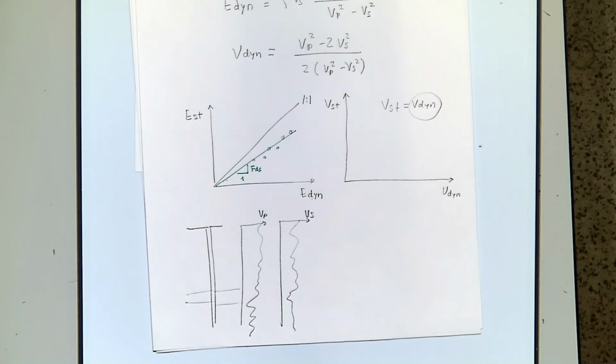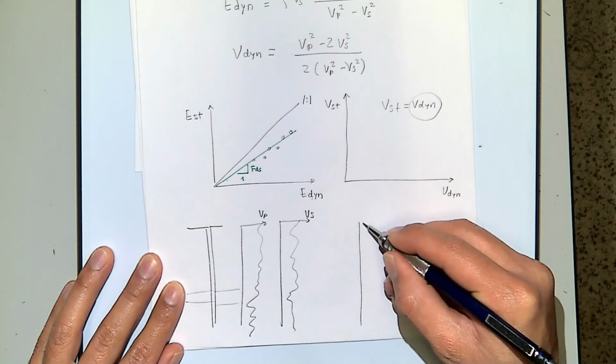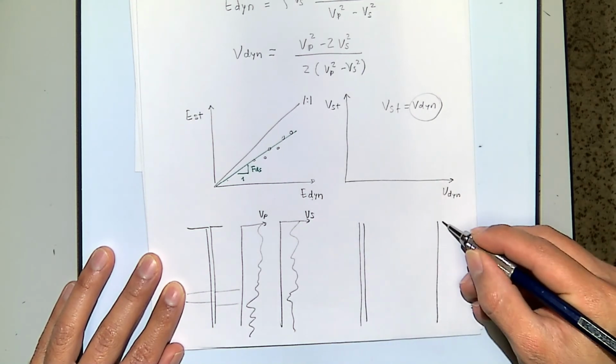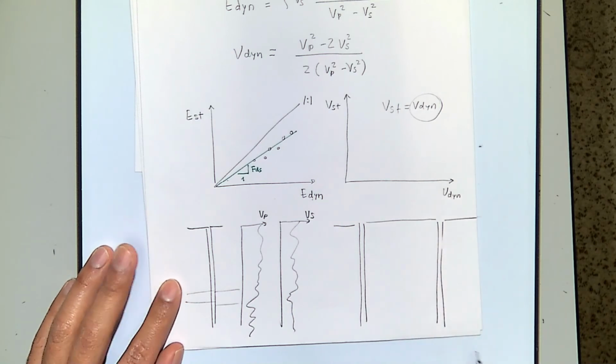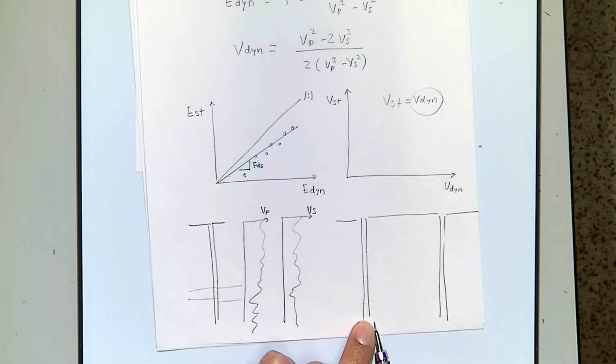With some other more advanced techniques, for example, if you have a crosswell setup, one wellbore here, one wellbore over here, you can resolve not only the variation in this coordinate, but also in that coordinate. You can do a tomography, so you can get the 2D picture. And if you have 3 wells or more and some other data, you can also get it in 3D.